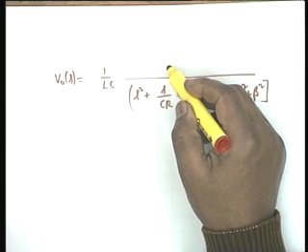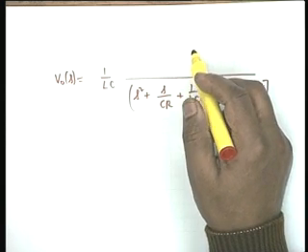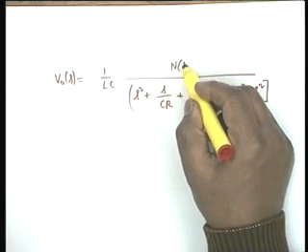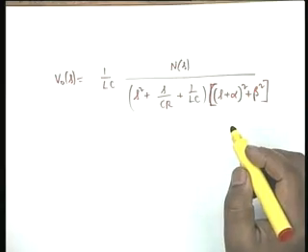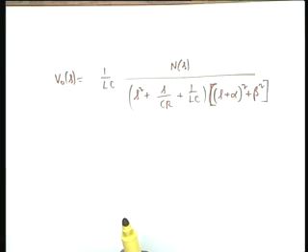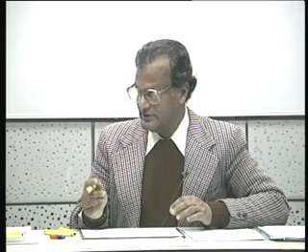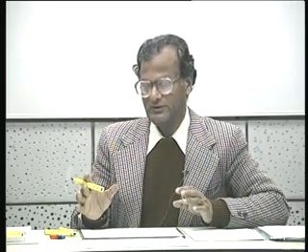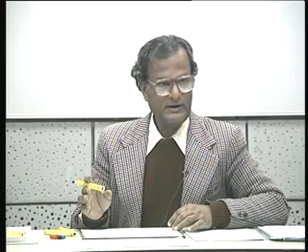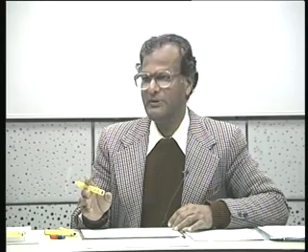And in the numerator you have a cubic polynomial. Okay, let us write this as n of S. I do not want to write this expression again, because part C says do not invert. You just give me a possible location of the poles, and then give me the form of the voltage response in the time domain.